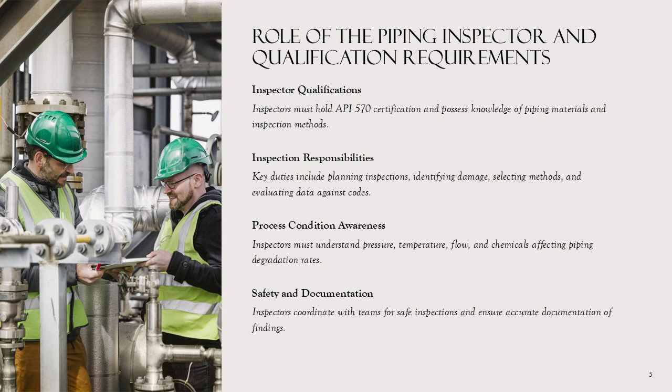Inspector competency also includes familiarity with non-destructive examination (NDE) methods, limitations of each technique, and awareness of human factors such as access constraints and inspection bias. Ultimately, the inspector serves as the link between code requirements and practical field execution, ensuring that inspection activities support safe, reliable, and compliant plant operation.